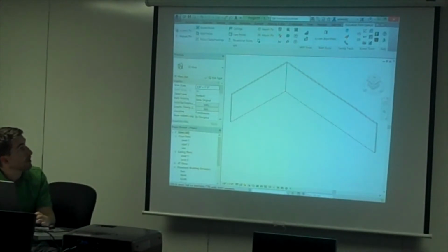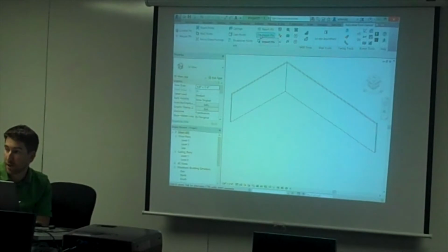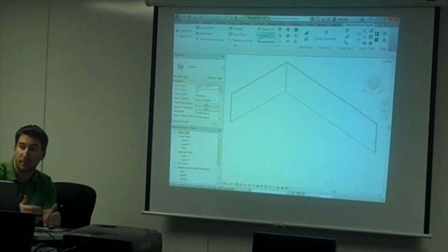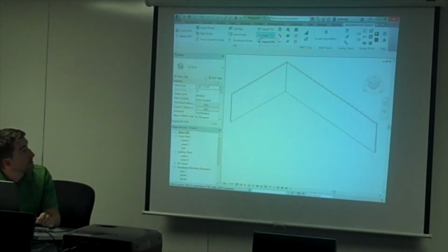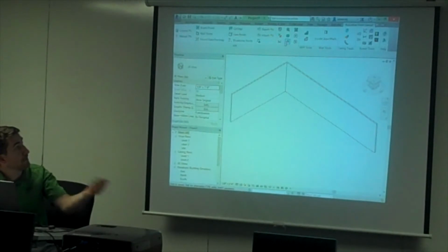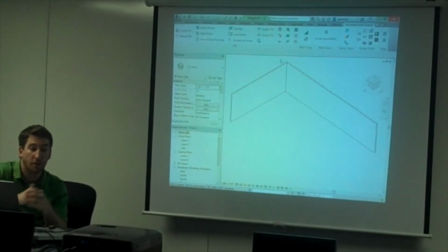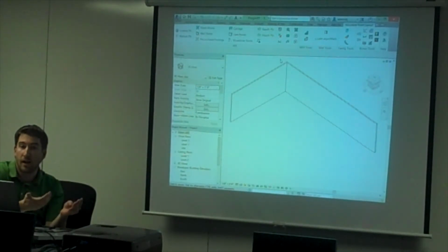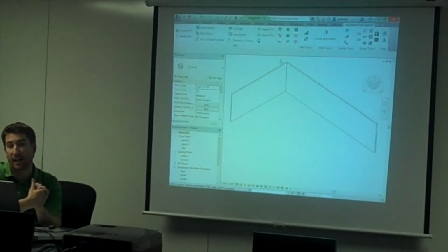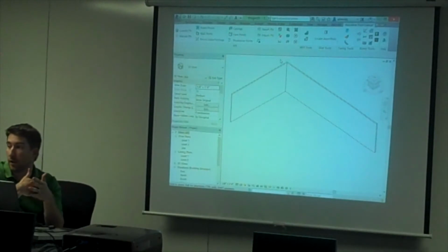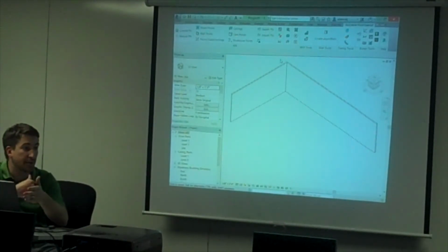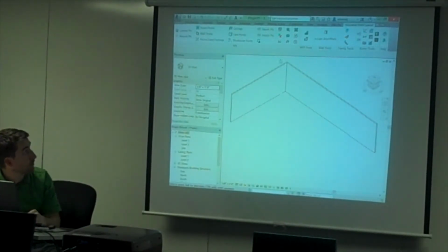It helps you when you're importing and exporting the points to kind of bridge the gap between maybe an architectural feet inches world and a decimal feet sort of surveying world. And so you can manage the points in here, you can create the points in here. You can do some stuff coming back the other direction, so you could go shoot the built environment and then use it to bring those things back into the models, and you can use that to kind of compare where you intended to be and where you actually ended up. And so I think that's kind of the way most folks are using it.